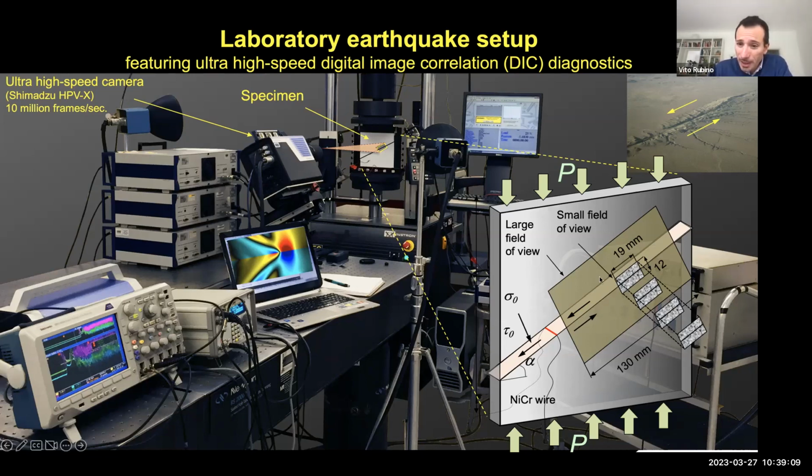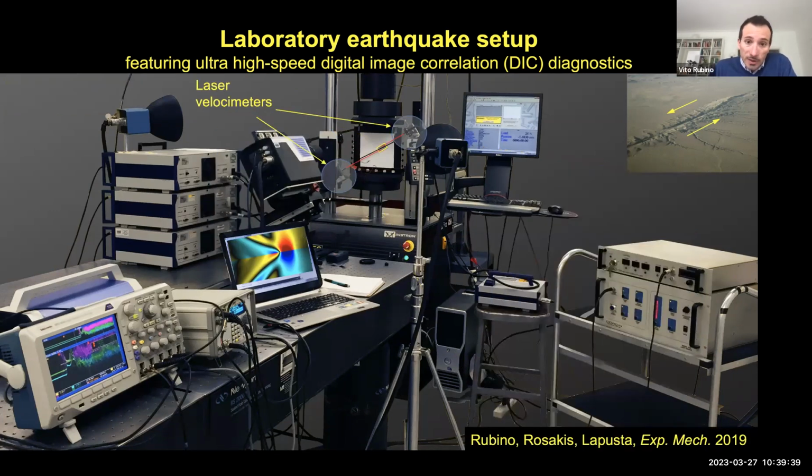And then we focus on an area of the specimen where a high-speed camera here looks and can take images at a speed of up to 10 million frames per second. So naturally, when we scale down earthquakes from the size of kilometers to the size of millimeters, we also reduce the timescales from seconds to microseconds, and therefore we need an ultra-high-speed camera to capture the process. And I will explain in a minute how the acquisition works. Then we also have laser velocimeters that can capture accurately the temporal evolution of particle velocities, and strain gauges, which can be deployed in selected configurations. Not shown here though.